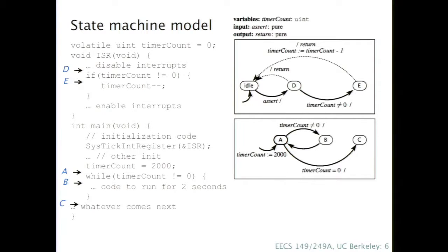Well, yes, that's right. So the transition from B to A has no guard on it. And in our notation, that's just a shorthand for the guard is a Boolean that evaluates to true always. So this transition will trigger. If you're in state B and the machine reacts, we will move from B to A. There's no question. There's nothing to test.